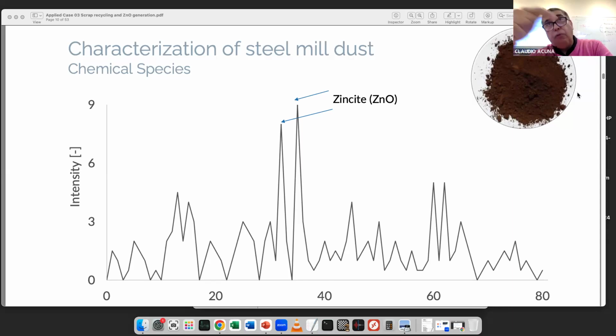Okay, in short, you can have first X-ray fluorescence to determine a specific element. That will be fluorescence, XRF. But in this case, we have XRD. D stands for diffraction. You are changing the angle of incidence, XRD. And that can show you the fingerprint of a specific element. If you have sulfate, you have a different shape of this curve. Here is the angle of incidence. In the same way, when you have FTIR, you know FTIR. It was mentioned yesterday. Professor Tania Sandoval, student. FTIR, Fourier transform infrared.